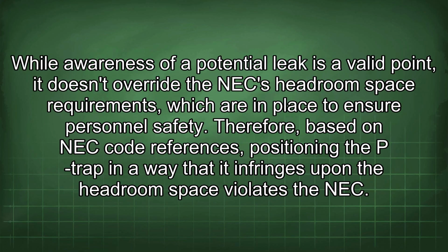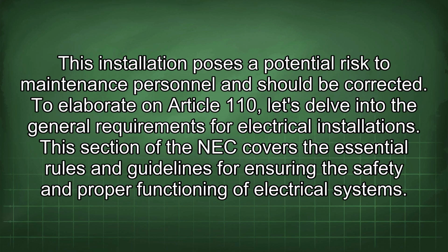While awareness of a potential leak is a valid point, it doesn't override the NEC headroom space requirements, which are in place to ensure personnel safety. Therefore, based on NEC code references, positioning the P-trap in a way that it infringes upon the headroom space violates the NEC. This installation poses a potential risk to maintenance personnel and should be corrected.